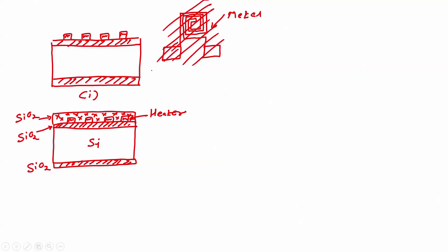Now, if I ask you to tell me what is the resistance of this heater, can you measure the resistance? You cannot, right, because there is an insulating material on the micro heater. But how can I measure the resistance? If I remove the insulator from the contact area, this is contact pad, then I can tell whether I can take a proper contact or not, or I can measure the resistance in a simpler word.